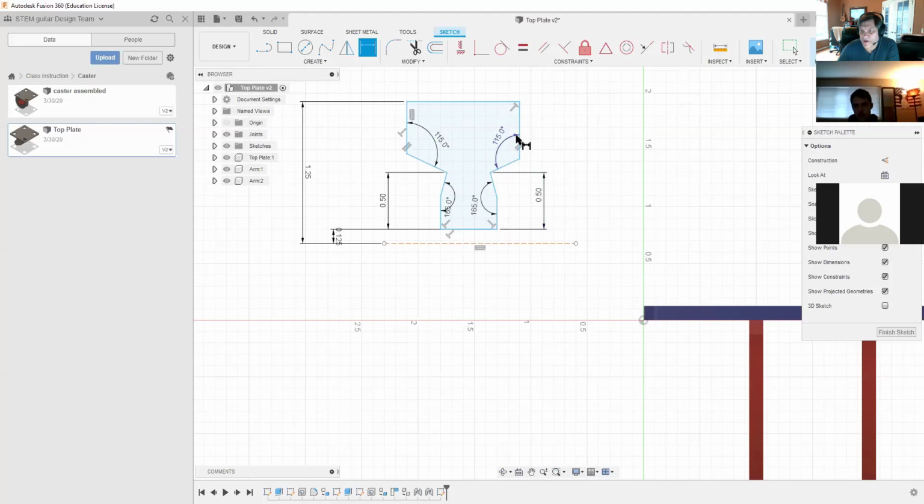Now notice the reason why I did that is I wanted to make sure that the angles held stable and that the object is centered. So now you can tell that it's still not 100% centered yet. So this is 1 inch wide. Well, we know that it's got to be 0.75 is the overall width. Uh-oh, that's not good. Let's undo that because that's no longer going to provide the distance that we need. So a 1/2 inch here, we'll say 0.375 here on the bottom.